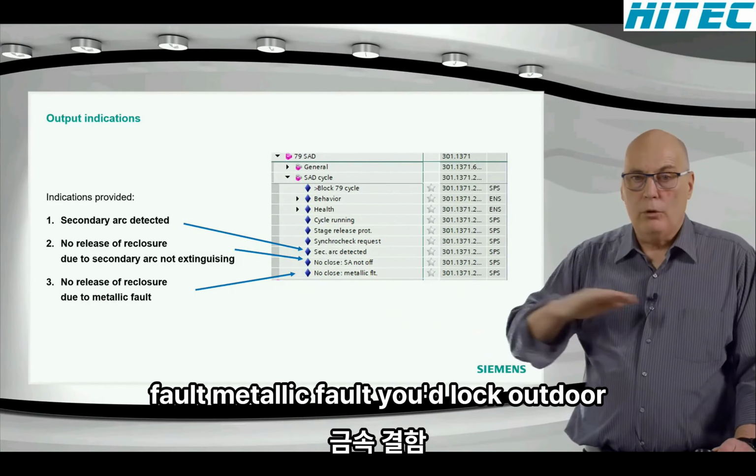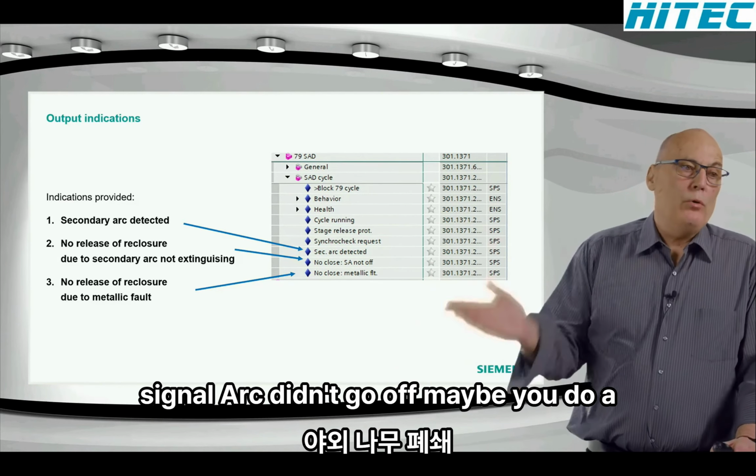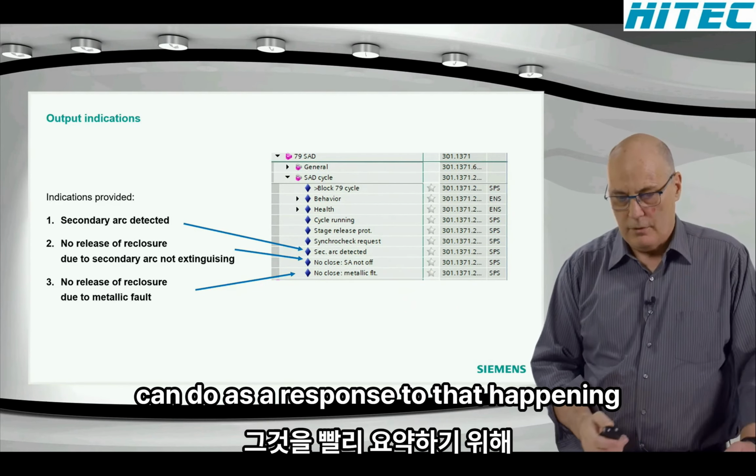Metallic fault, you lock out the auto reclosure. Secondary arc didn't go off. Maybe you do a three-pole trip and a three-pole auto reclosure. That's optional, what one can do as a response to that happening.